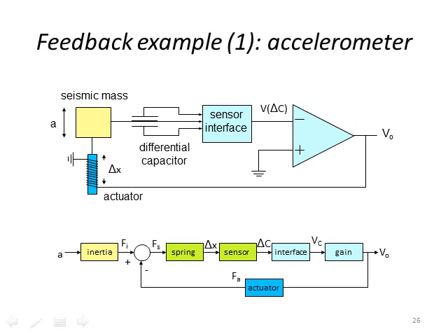And from the early lectures, we saw this accelerometer, which you will also use in your courses, in your practicum. Essentially, this consists of a mass. And in the accelerometer, this mass is included right on the silicon chip. It's a big piece of silicon that moves when you have a certain acceleration. F is equal to mass times the acceleration. And then we have a differential capacitor that basically measures the movement of that mass. So we measure the capacitance and then a sensor interface, and then we have a charge integrating amplifier that essentially accumulates the charge, and I don't show the feedback capacitors here, but that's essentially what's in the sensor interface.